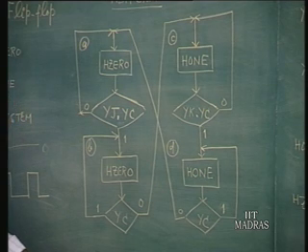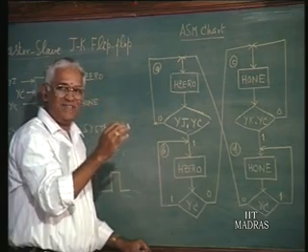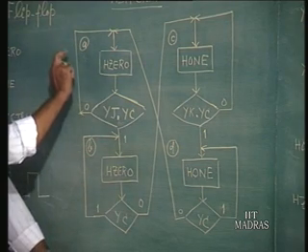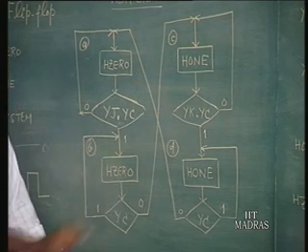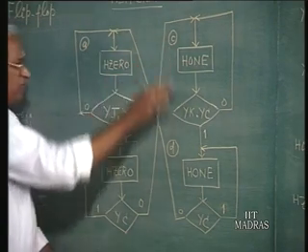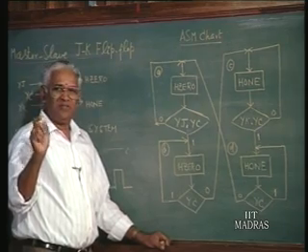Remember what it is we are talking about, the state memory. Go back and recall the generalized state machine model. We had a state memory, which is the one which holds all the states, and here we have 4 states. So that particular memory element must be either in A or B or C or in D. That's what it means. At any time the machine is only in one of the states. So for representing 4 states you need at least 2 memory elements, 2 memory cells.